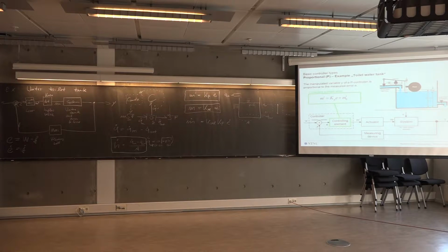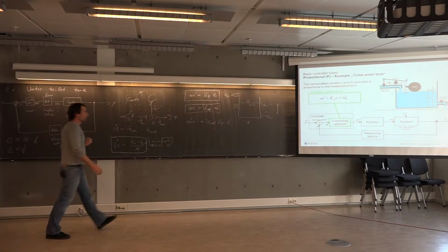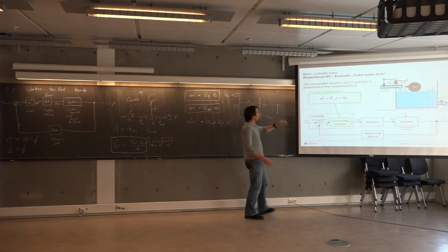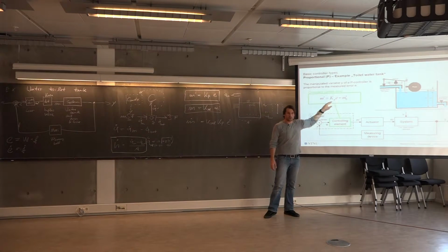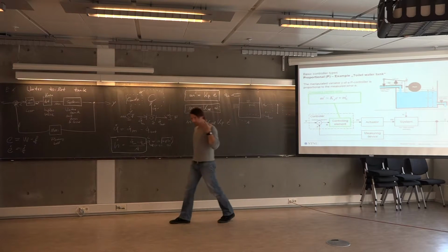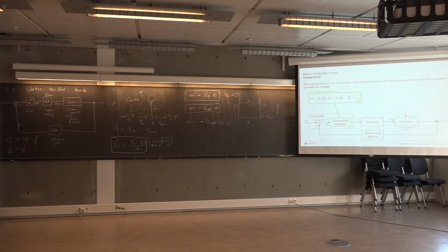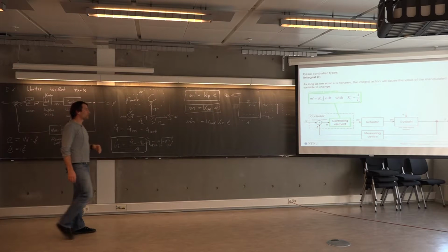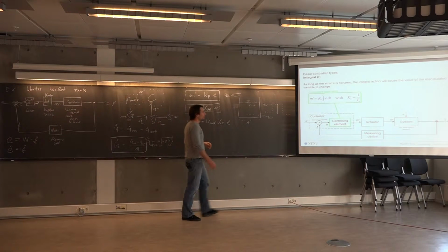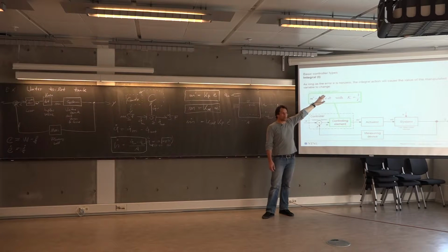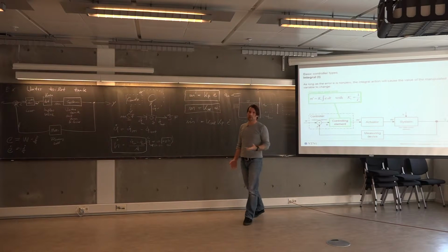Another concept of control is integral control. One final remark here. As mentioned, this equation considers the current error, the instantaneous error at this very point in time. Integral control considers the past error, or the history of the error.